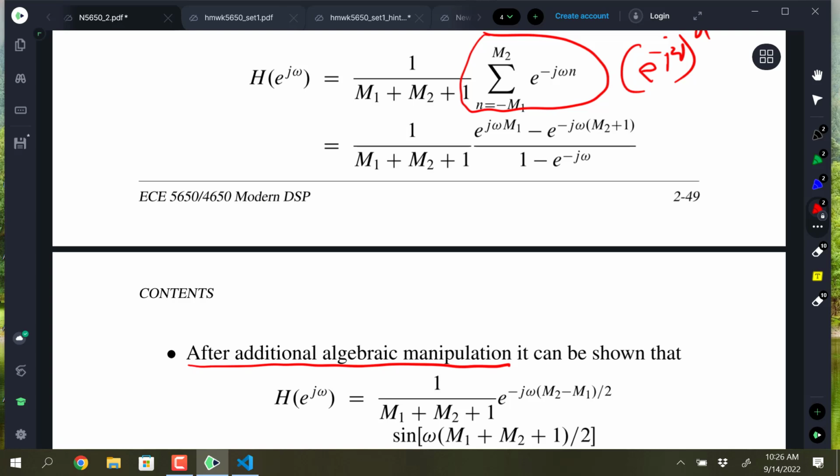The real trick to this is taking the difference between the two exponentials there, and from the outset you should be seeing that the ratios there are really two sine waves, because whenever you see an exponential with a positive argument minus an exponential with a negative argument, your brain is supposed to say, oh, that's a sine, right? That's in the form of a sine. There's got to be a 2j under that.